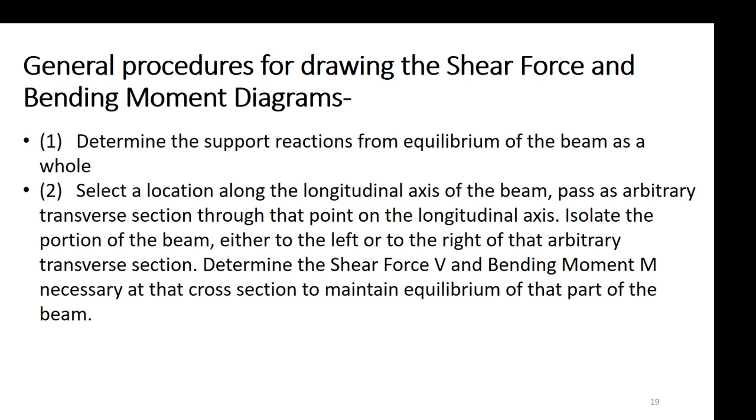We will understand better through examples, but I have to state it formally: we will determine the support reactions from equilibrium of the beam as a whole, select a location along the longitudinal axis of the beam, pass an arbitrary transverse section through that point, isolate the portion of the beam either to the left or to the right of that section, and determine the shear force V and bending moment M necessary at that cross section to maintain equilibrium of that part of the beam.